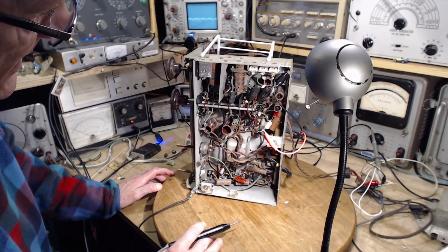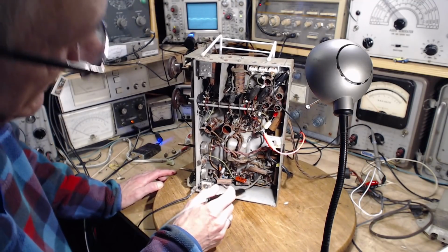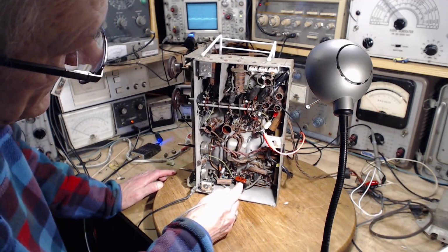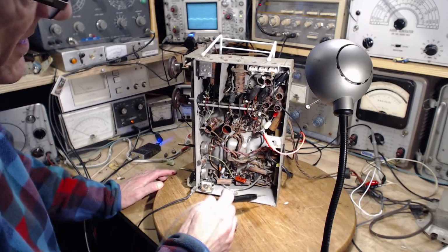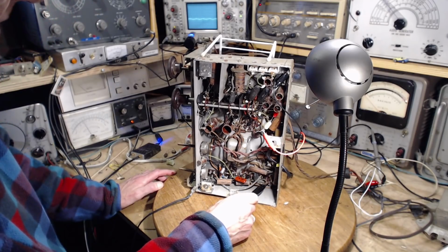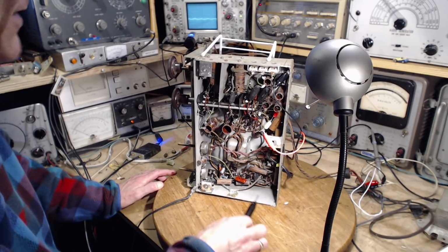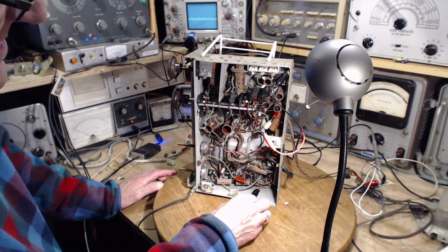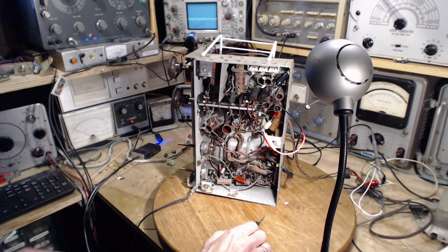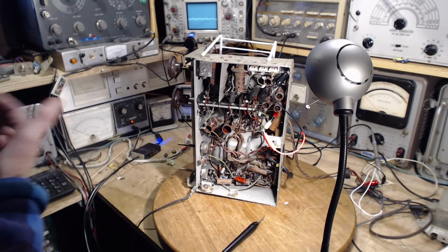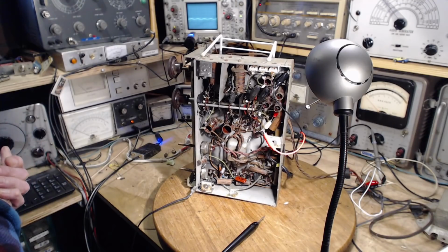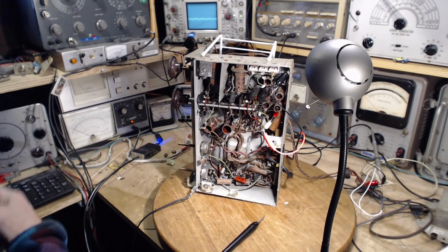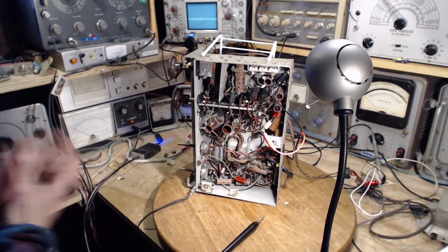Right. So I was going to look on the schematic and figure out where this pin should be getting its voltage from. Probably from over here, because there's lots there. So this is probably an open resistor. And then the question would be, why is that resistor open? Did it go open on its own, or did something force it open? If it was a shorted capacitor, it would probably burn it, and you'd see it. That's my thinking anyway.